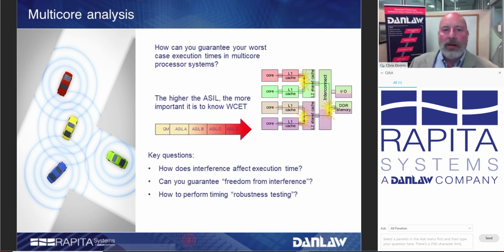Next slide here. So getting it right includes that the algorithm itself that runs on the core guarantees its processing with hard real-time constraints. In today's architectures, assuming an algorithm has unlimited access to shared resources like the caches or the I/O bus and other resources on the multi-core processor, it's pretty dangerous.